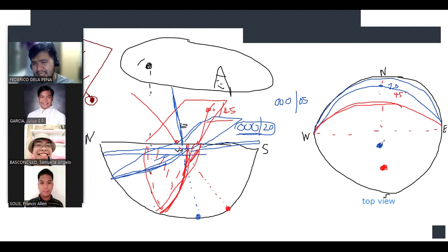So in a sense, the poles are going the opposite way. They basically go the opposite azimuth. You can see here the pole for this plane is actually on the other side. It's basically just a 180-degree azimuth. You're flipping the azimuth by 180 degrees, and second, you're also flipping the dip angle by 90 degrees. Okay.